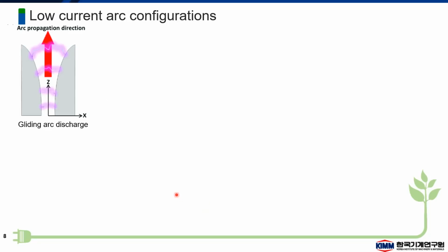So first of all, we will discuss the famous classical gliding arc. In a classical gliding arc, we have two diverging electrodes. When we apply a high potential between the two electrodes, an arc generates at the shortest distance, and with the flow of gas, it glides on the surface of the electrodes. The problem with this type of gliding arc system is that, due to its 2D geometry, there is less interaction of plasma with gases. In this way, we get low conversion of gases.